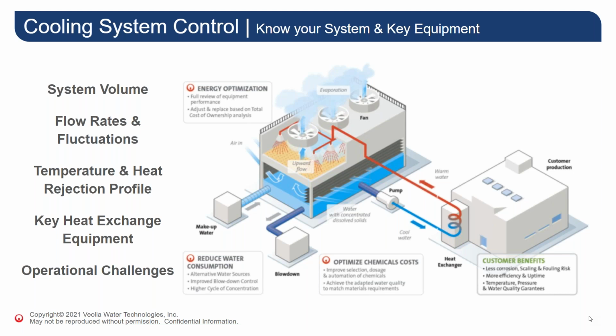It then passes through a heat exchanger of some sort, picking up heat, and then onto the cooling tower to reject that heat via evaporation. Then back to the heat exchanger to pick up more heat. To ensure that the cooling water accepts the heat from the heat exchanger, the exchanger surfaces must be free of deposits and microbiological growth. To demonstrate how dangerous these deposits can be, even 1/16 inch of scale can decrease heat transfer by up to 50%.